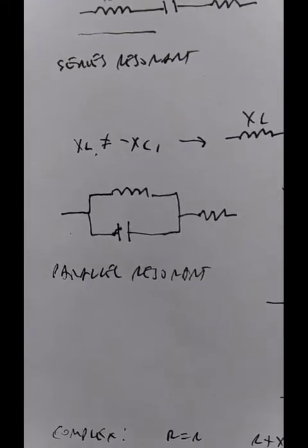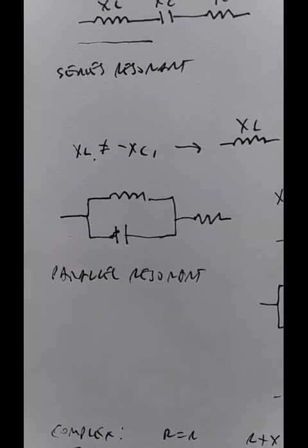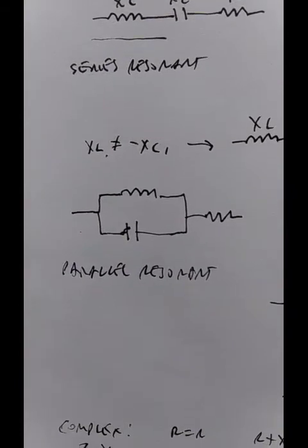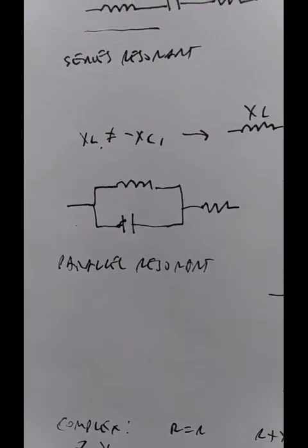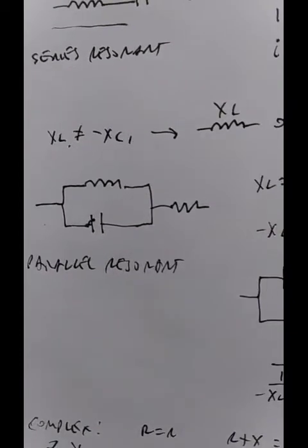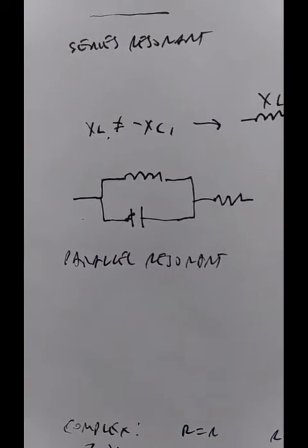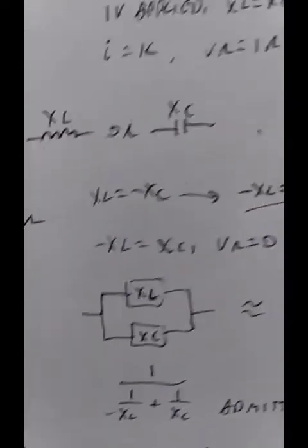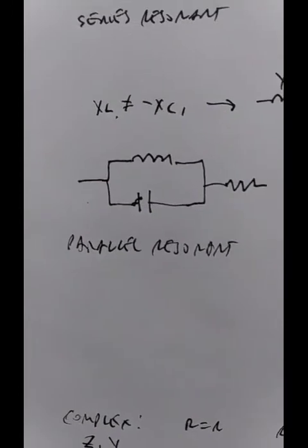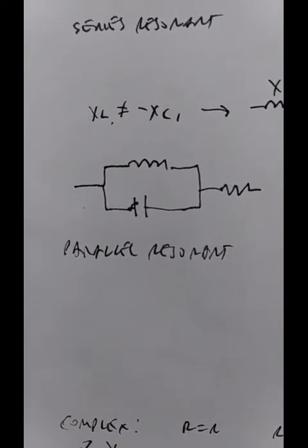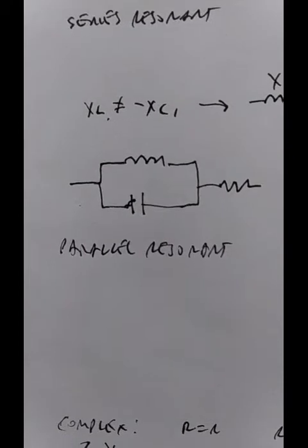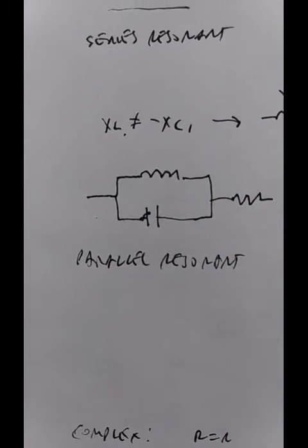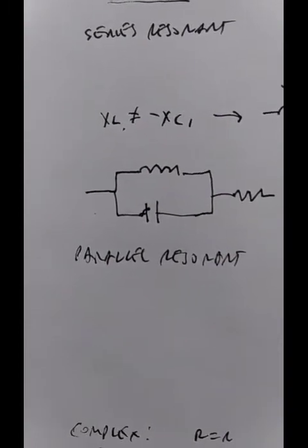In a parallel resonant circuit, parallel LC with a series resistor, the resistor can also be in the inductor or capacitor branch. That complicates things quite a bit. It'll actually change the frequency, believe it or not. I read it in the book. I didn't quite believe it. I calculated, and sure enough, it does. The characteristic of a parallel circuit is that the voltage is the same across each component, but the current is different. And inverse to the series resonant, when the voltage is the same, the current is multiplied by the Q. Can get very high current.